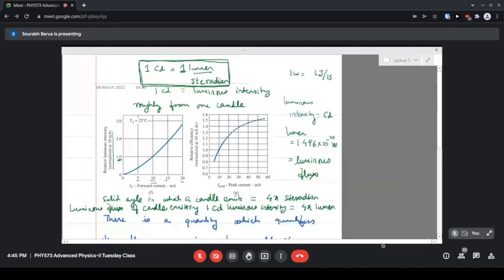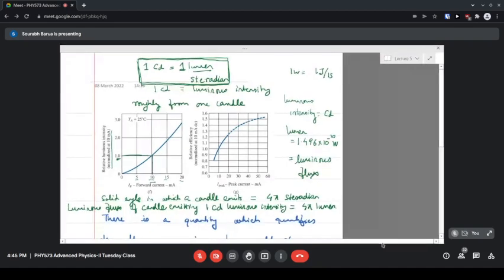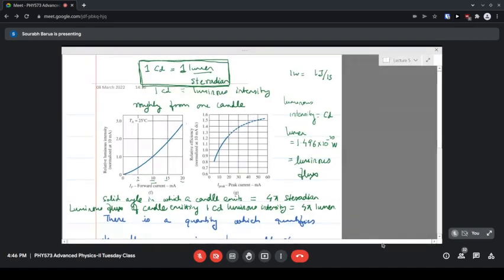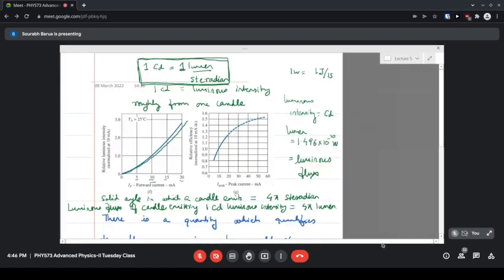And you can see that the luminous intensity is increasing. At 15 it is becoming twice that at 10. At 20 it has become almost thrice. So basically the luminous intensity, or the light emitted per unit time per unit solid angle, is increasing almost linearly as you increase the current. All right. But as I said, it will also saturate at some point.